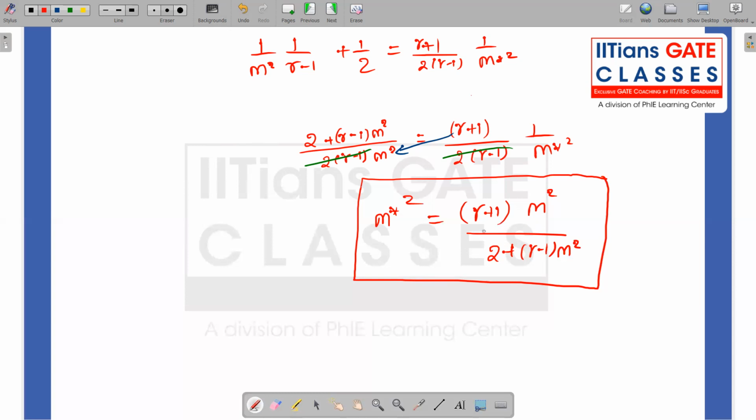Now from this we can see different ideas, right? One is, what happens if the local Mach number is 1? If the local Mach number itself is sonic, then what happens? If M is 1, this becomes gamma plus 1 divided by 2 plus gamma minus 1, which again becomes gamma plus 1 by gamma plus 1, so both cancel out. So if M is equal to 1, then M star is also equal to 1. Now, what if M is subsonic? If I put M as subsonic over here, that gives me M star also subsonic. If M is supersonic, then M star is also supersonic.